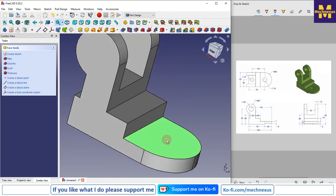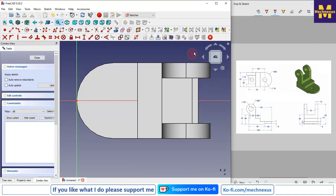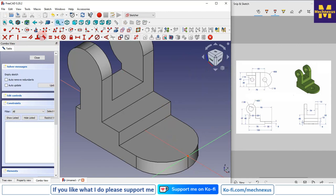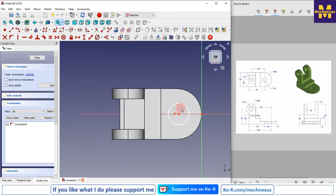So first I will select this face and create a sketch on this face. Now I will draw the circle because this is a very plain hole, so I will not use the hole feature. Now switch to the top view.